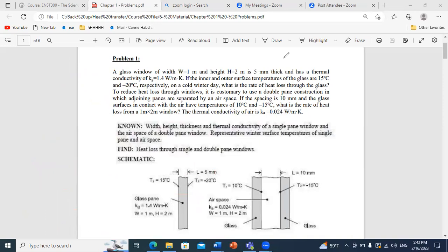We'll see together that by introducing double glazing we will reduce heat losses a lot. What is the idea of double glazing? First, instead of one layer of glazing, we use two layers. So of course, we already have increased thickness. But now I'm just talking about glass. For glass, what we did is we increased the thickness, plus we added in between an air layer.